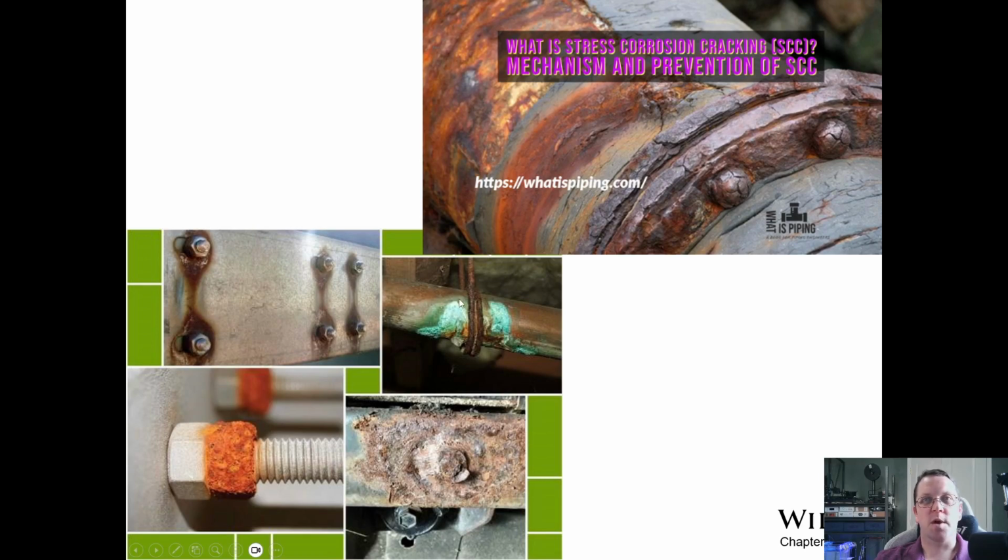Similarly, something like this water pipe under a house, this appears to be copper. Usually when you see a blue oxide, that's a good indication that there's copper present, a blue-green color. You saw the copper sulfate solution that was a very deep cobalt blue color. So copper pipe that's corroding because it's paired with this steel hanger, and this appears to be up underneath a house. This pipe is corroded probably very much to the point of leaking because of the dissimilar potentials between the steel and the copper pipe.